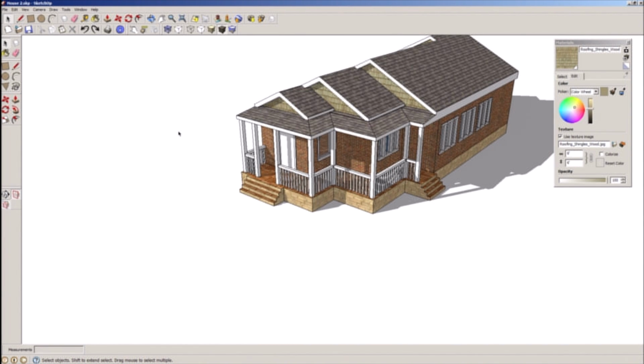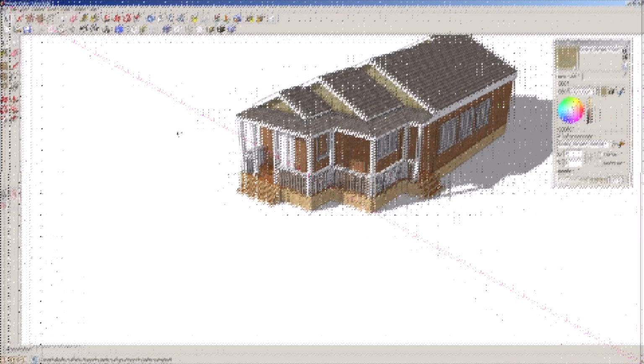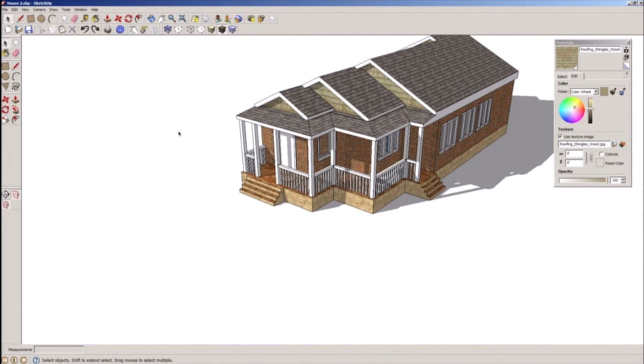With back-facing polygons, I'm just going to say a few things. Back-facing polygons cause some problems in the Virtual Property Architect client, because the client is a traditional real-time 3D environment, where the front face actually matters for things like shaders and for collision detection.